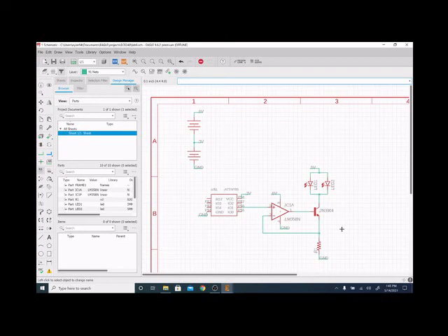So 40 milliamps with a 3 volt drop, let's see, 3 divided by 0.04 is the same as 300 divided by 4, which is around, oh goodness, math, don't fail me now. Let's see, if we divide it into quarters, that would be 25 times 3 is 75. Okay, so we need this to be a 75 ohm resistor.